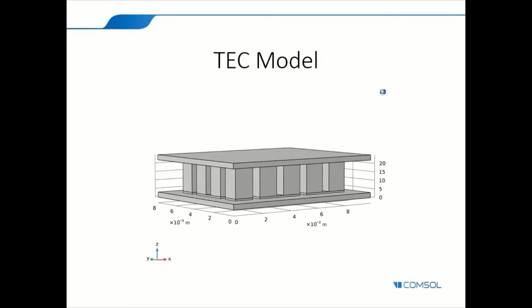Basically, the thermoelectric cooler is made out of very small piles of the semiconductor. Each pile, or each column, is made out of a P junction or an N junction of this semiconductor. There are certain specifications for this semiconductor. It has to be conductive to a certain extent to eliminate unnecessary heat generation due to resistance. And it also has to be more or less non-thermally conductive to a certain extent, so it is not able to transfer the heat generated on one side to the other and ruin the whole cooling effect of the device. Other properties can also be necessary for these operations.